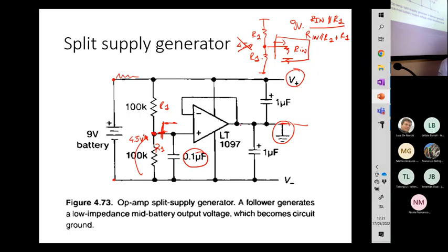Okay, while if you had this voltage buffer, since the input impedance here is very high, even if you plug the input impedance of the op-amp here, the parallel between a very high input impedance and R1 is R1. Okay, so you fall back in the desired R1 over twice R1 voltage divider effect. Okay?